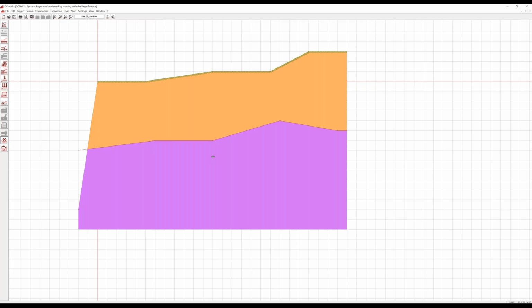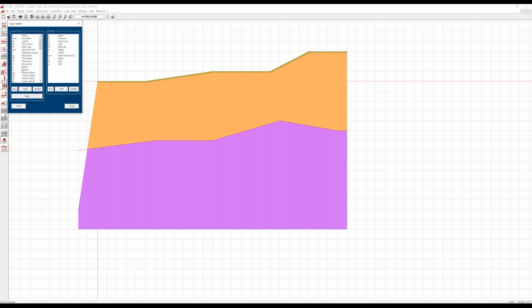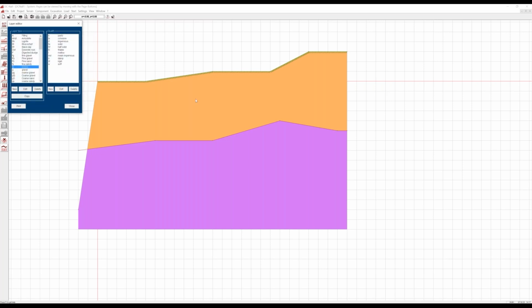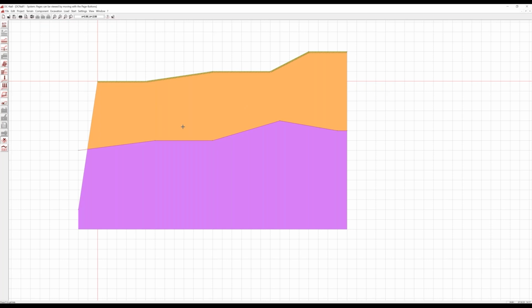And these colors are used if they are predefined. Under settings, we have a so-called symbol editor. And here, any soil name may be defined with a short designation, G only for gravel, or a long text. And this gravel can have a color yellow. And if the defined soil name, here sand, for example, is found in this soil editor and the symbol editor, then the color is used to display the specific soil layer here.